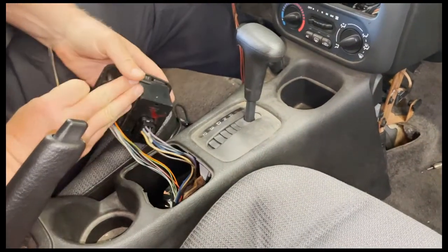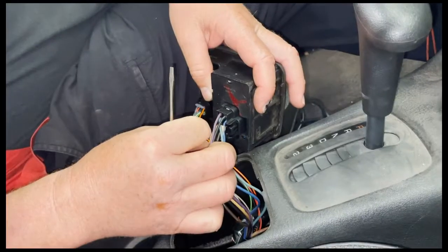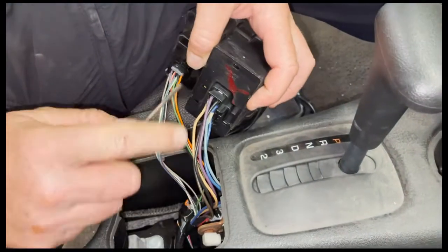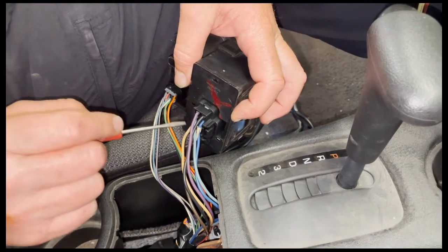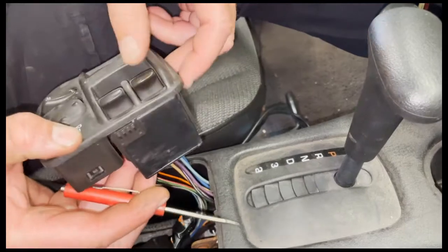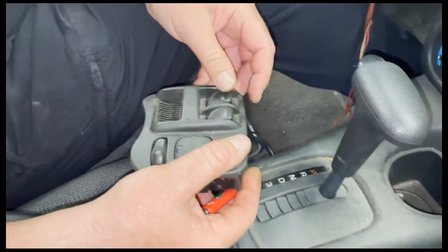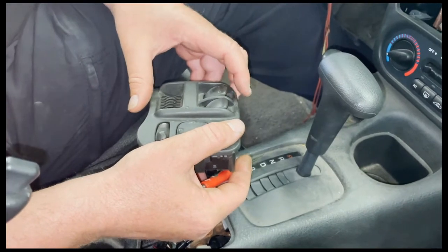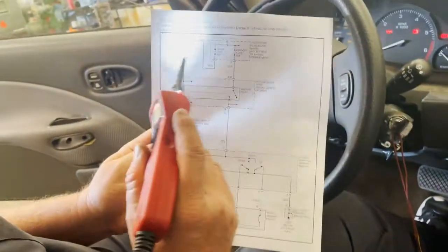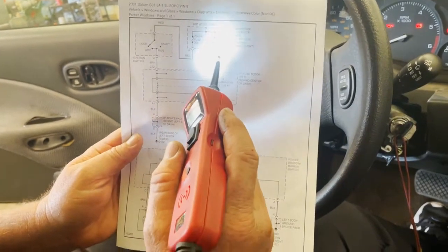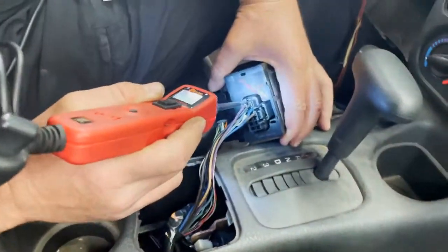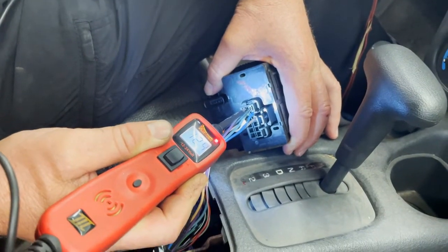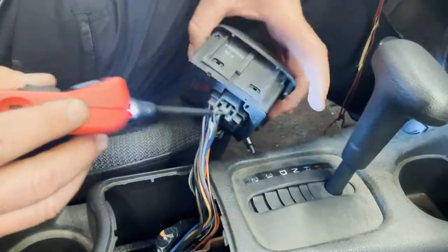So I'm going to turn it over, and then we need to consult with a wiring schematic because I know we had a blue wire and I think we have a brown wire, but we want to know what wire works for the one switch right here, which is the driver's door. So we got to refer back to the schematic. My ignition key is on, the relay is on. I should have power going to my purple wire going to my switch box right here. Should have power with the key on. And I have 12.4 volts at the purple wire going into the back of my switches.